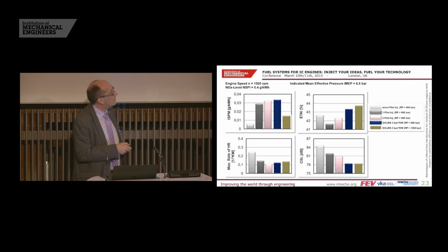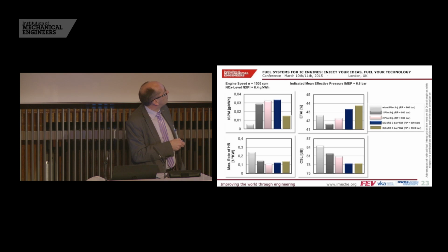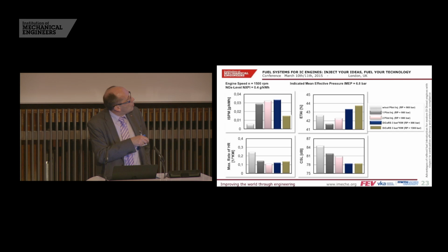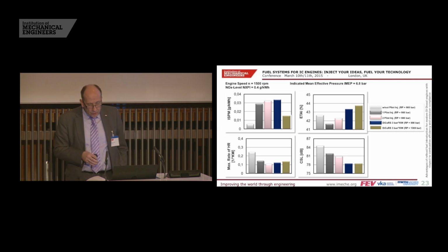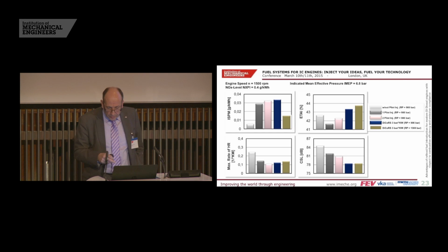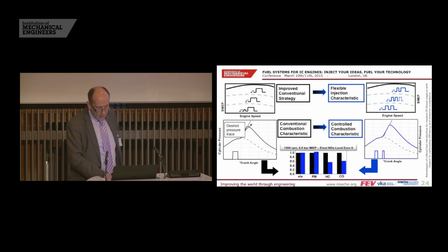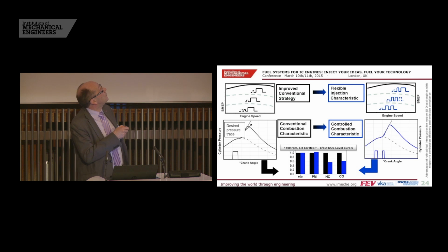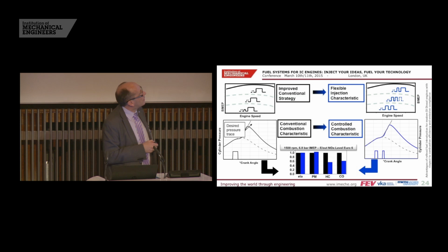getting a quite smooth, silent, quiet engine by controlling this burning rate while utilizing high injection pressures with a given constraint on the maximum degree of pressure rise, here set to 3 bar per degree crank angle as the limit for the optimization. So this finally leads then to the summary here. We are currently in the field operating the engines with more or less improved, more sophisticated conventional injection strategies, shutting off pilots more or less. Nevertheless, we are, let's say, linked to certain limitations.